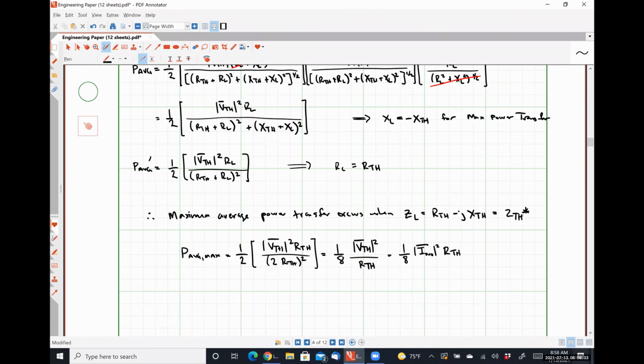But a reverb circuit for a guitar effects unit is literally that. It's just an LC tank that makes it ring in perpetuity. Old school reverb circuits, though, are not done using inductors and capacitors. It's actually a spring. So that's why they're called spring reverbs. But yeah, that is how you convert a DC signal into a ringing oscillatory tone. Or one way you can convert a DC signal into a ringing oscillatory tone.